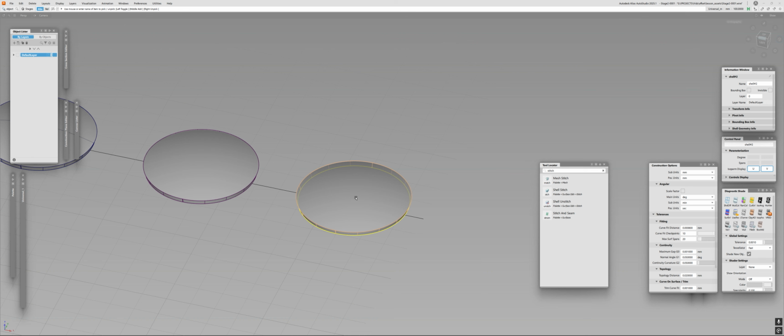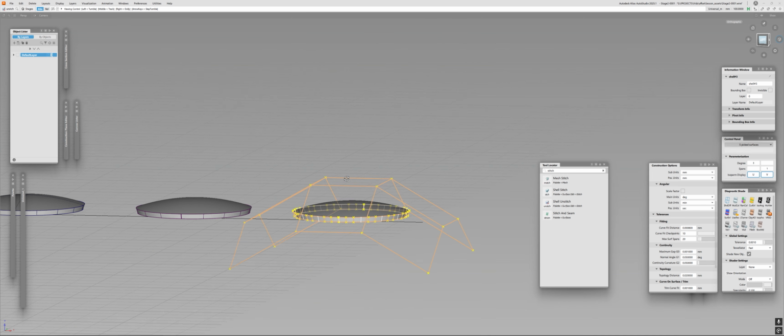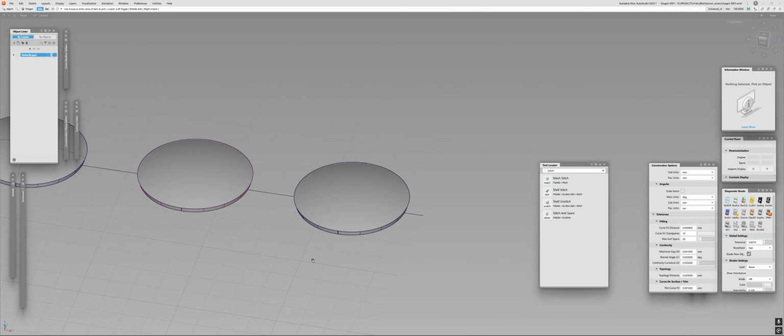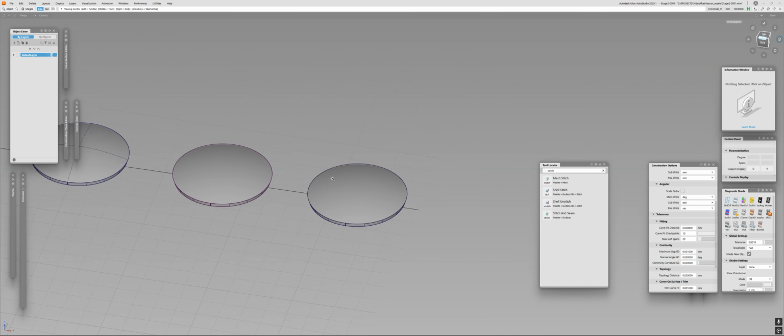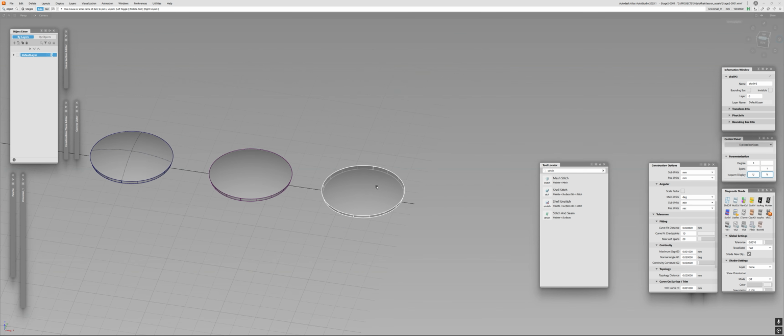And surface modeling tools, when it comes to BREPs, strip all the controls away from you. So if you want to proceed, you need to unstitch. We have this option called unstitch, and I can unstitch it now, and you're going to see I have all this stuff back. But true solid body modeling tools can actually work with these stitched versions, and they can work with solids. The moment you convert it to a solid, you can do fillets, you can do Boolean operations, stuff like that. Now, we can do Boolean operations in Alias too, but the options are quite limited.